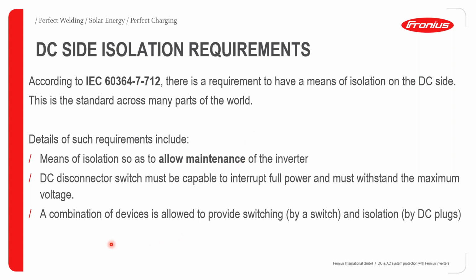A combination of devices is allowed to provide for switching. This can be a manual switch or isolation by things like DC plugs. If you're looking at things like MC4 plugs, these can be used as well for isolating the DC part of the system.